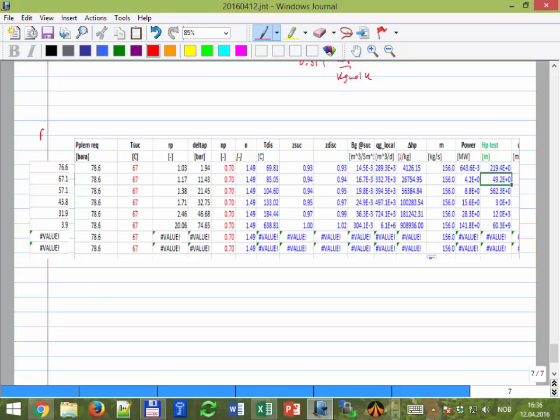Where do we violate? This is pressure at the suction, and this is in bar. We said that the pressure has to be greater than 20 bar. So where do we have a violation? In this year. This was 21, 22, 23, 24, 25, 26. So in year 6 of compression, we are going to have a problem: the pressure at the suction is less than 20. So we have to take some actions here.